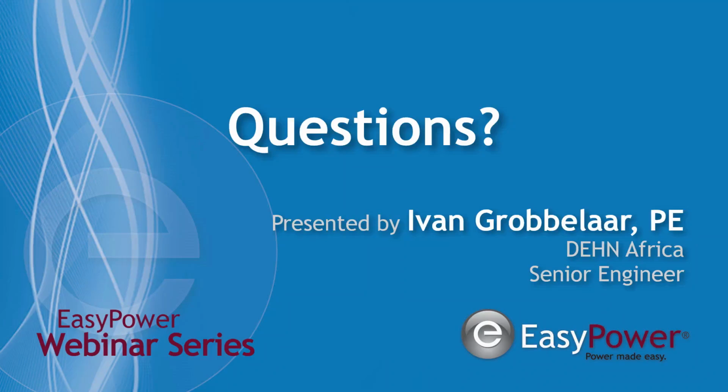Another question that we got was regarding soil resistivity, and how does this affect the performance of the earthing grid during lightning strikes. Yes, soil resistivity definitely does play a role. The standards don't make specific reference to that in that specific standard. However, in some hidden parts of the main lightning protection standard, they do talk about 400 ohm meters, but it shouldn't be a very big concern when you work with something as small as a 20 meter by 20 meter or 40 meter by 40 meter mesh.